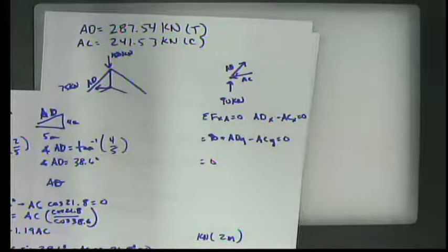Now, you may be getting mixed up if you did the method of sections in statics, because when you do the method of sections in statics, it looks a little bit more like what you're describing. It's exactly the same idea. But what we're really looking at is just this joint, and anything that's affecting the joint, we view as a structural member bearing a force. And is that force pushing on the joint, or is it pulling on the joint?